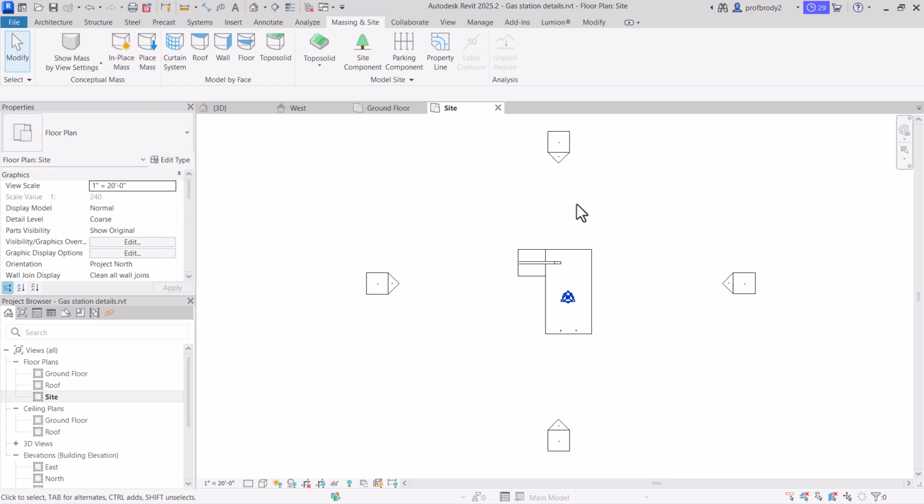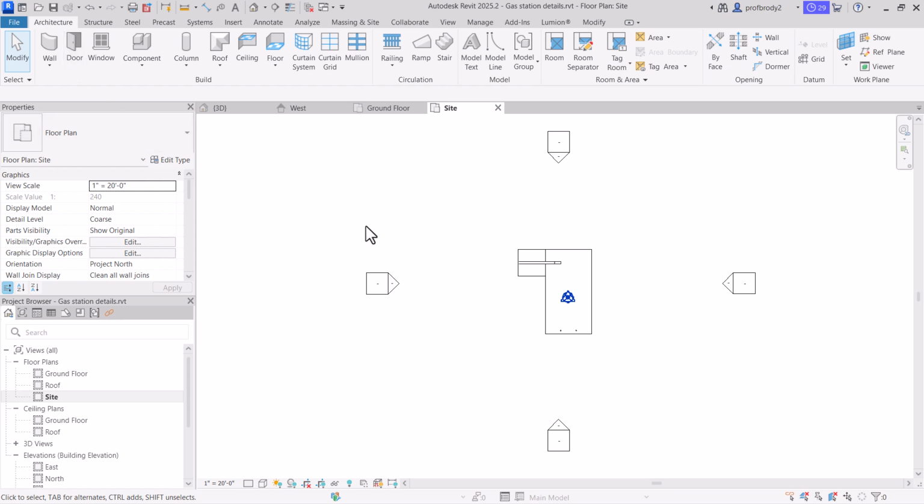Or if you want to build around a very specific thing, make a built-in seat around a column, for example. But the disadvantage of masses is they don't play well with other features of Revit, including things like the visibility and graphic overrides menu, which can turn on and off elements by their category, by their type.